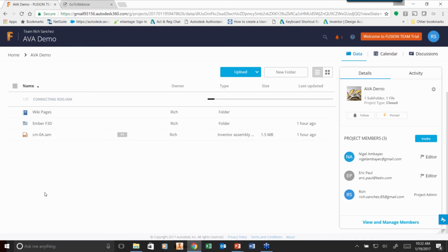So I think that answers Adam's question. You do have to have the part files up there for the assembly to know that they're there, but you don't have to do them individually. If you just, as Rich did, select the assembly, send it over, it's going to search your machine for those part files that are associated with that assembly and move them over, as opposed to someone who's using Dropbox per se, grabs that assembly file, puts it in their Dropbox, someone else goes to open that assembly, and you have to resolve thousands of links for parts.